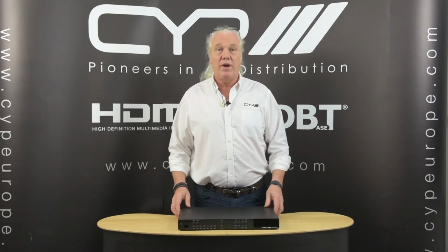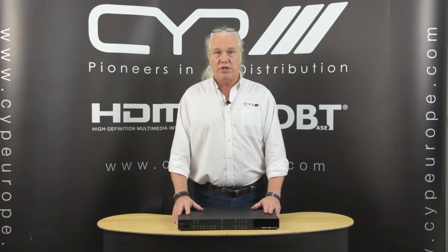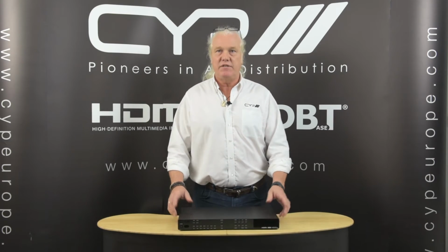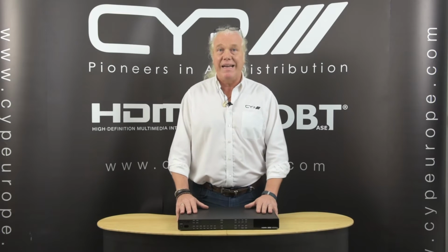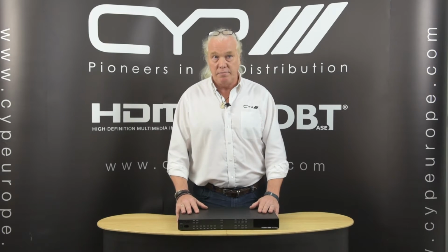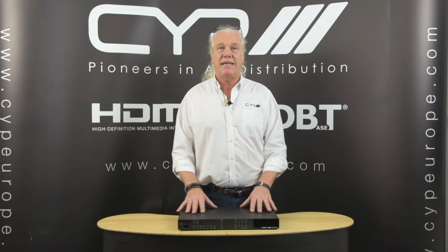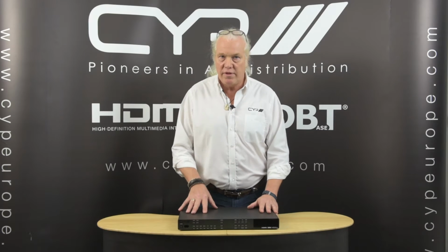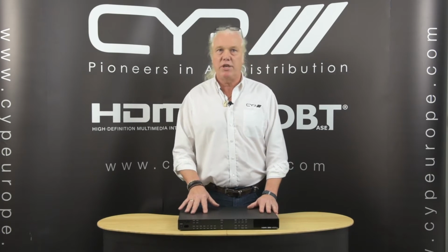So today we're here to look at one of our new products again, and this time we're looking at the OR-HD62CD-4K22. The 4K22 means that it is 4K UHD supporting all the way up to 60 Hz at 420 colour spacing. It's also fully HDCP 2.2 compliant. So it's a 6x2 HDMI matrix switch. That's 6 HDMI sources to 2 independent HDMI outputs. Both of the outputs have audio de-embedding, so there's an optical output dedicated to both HDMI outputs.